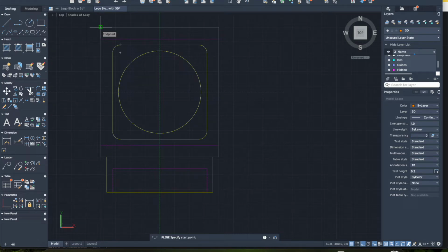So click in the corner, go across, and if you look at your drawing, this has a distance of 100. And then you come down and it's 110. And then you come across, it's 100, and then up 110. And then hit spacebar to trim.